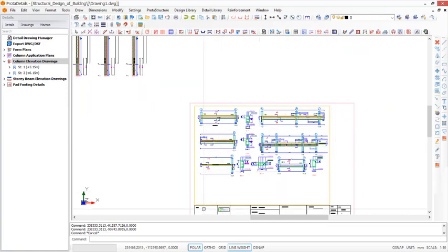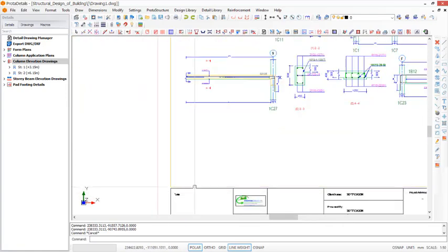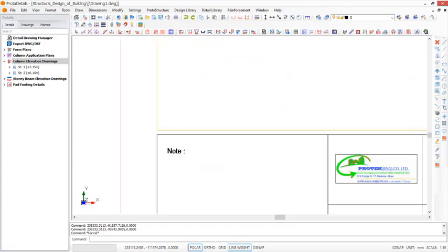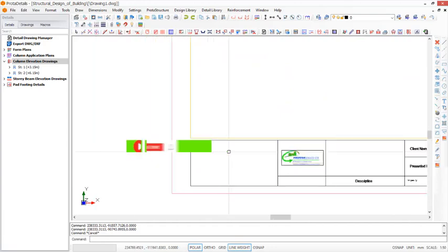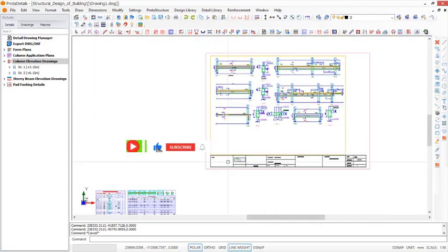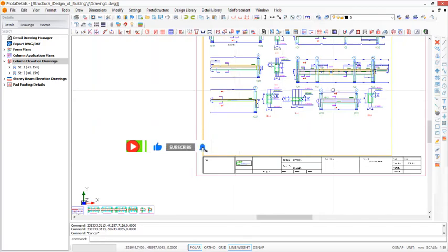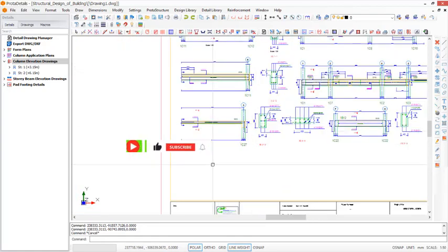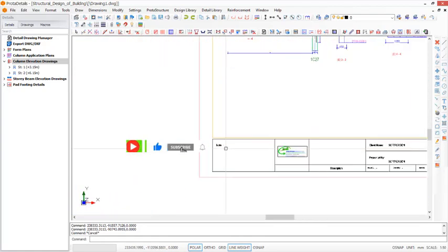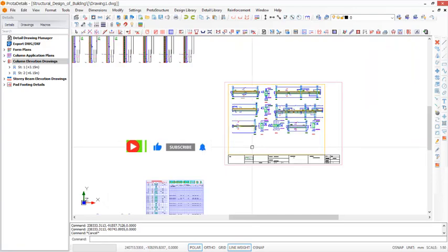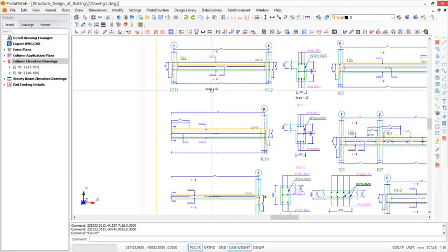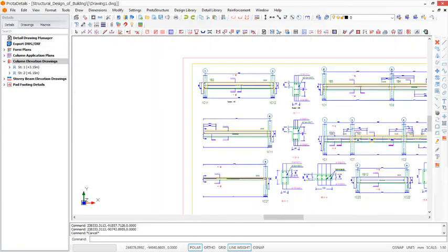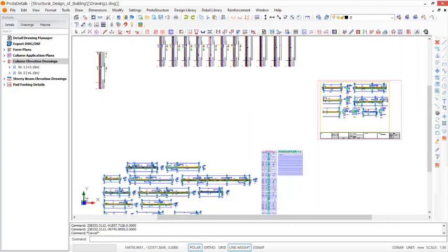Or you can just come to this note provisions and put a note: the scale of the drawing. The main drawings of the beams is 1:50, and then the sections is 1:25. You can just label it here in the note provisions, and that will take care of putting it under the beams. Okay, so that is well explained.